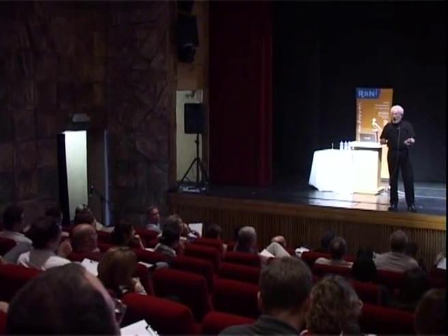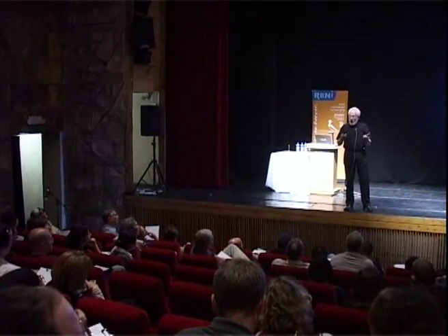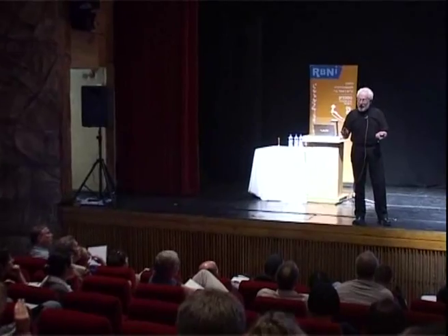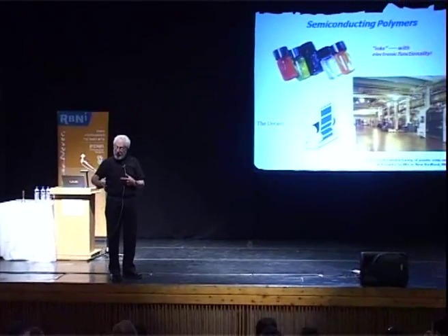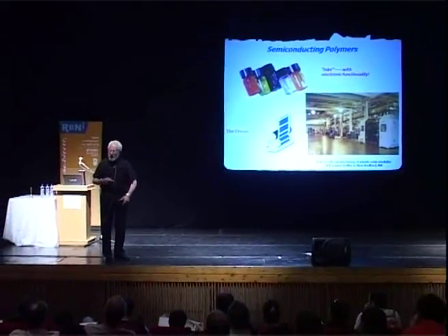It works. But it's a plant that was built by the Polaroid company to make multi-layer films for photography, right? And Polaroid went into bankruptcy, and so Konarka was able to buy a $250 million plant for $5 million. It's almost ideal. What goes on here is there are big vats where you can control the temperature of the solvent. There's a heater which controls the temperature on the roll. Behind this are 100 feet with 4 separate drying zones with different temperatures that you can control. So you begin to see what you can do.